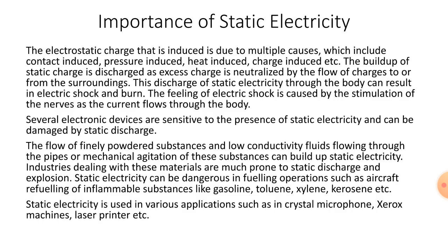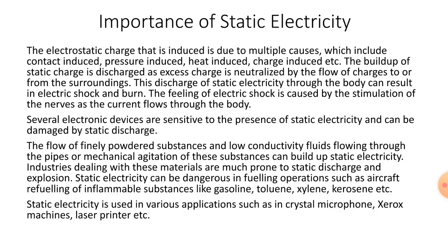Several electronic devices are sensitive to the presence of static electricity and can be damaged by static discharge. The flow of finely powdered substances and low conductivity fluids flowing through pipes, or mechanical agitation of these substances, can build up static electricity. Industries dealing with these materials are much more prone to static discharge and explosion. Static electricity can be dangerous in fueling operations such as aircraft refueling of inflammable substances like gasoline, toluene, xylene, kerosene, etc. Static electricity is used in various applications such as crystal microphones, Xerox machines, laser printers, etc.